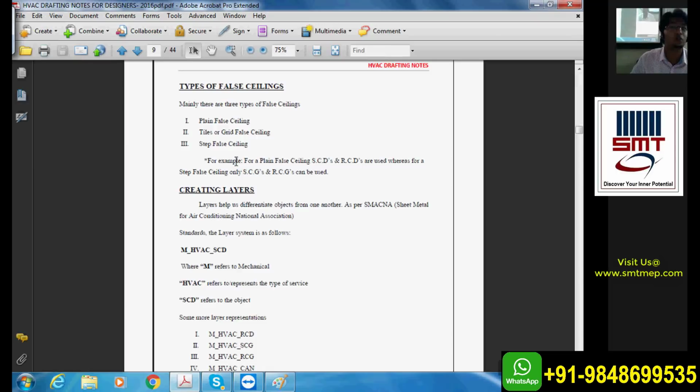Right. Now if there are individual diffusers, the machine is also going to work properly. There is enough amount of CFM to come out from the supply. All right. Now what happens is that when you calculate or purchase a big complete grill, that is going to initially cost you less than selecting individual diffusers. So every marketplace or everyone tries to purchase that and put it there, thinking as long as air comes, it is fine. All right. So it's better to follow the actual principles and actual procedures on how to do things.